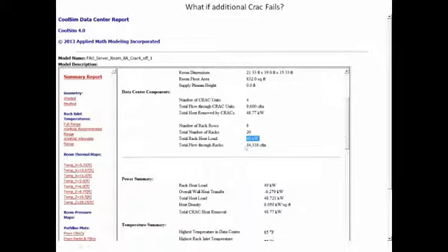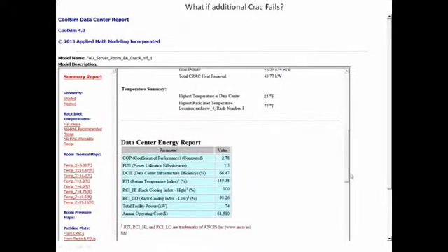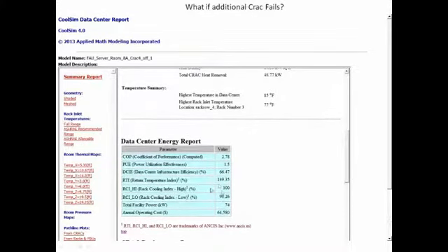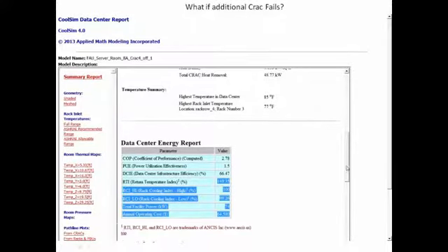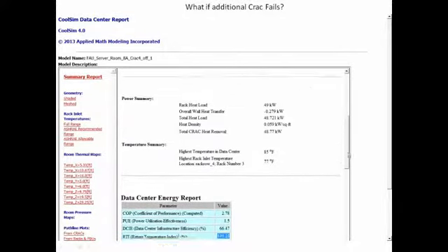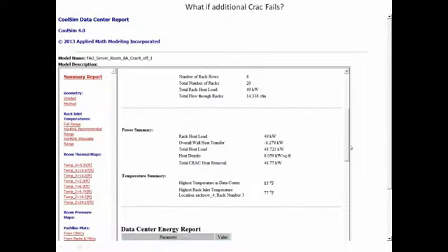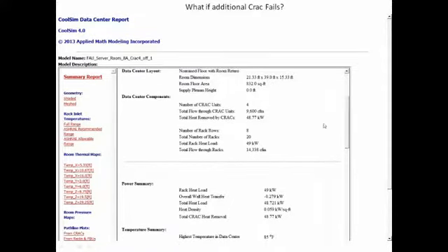But what happens is the flow rate through the racks goes to 14.3. That actually improves things a little bit. But my RTI is sitting here now at 149. I still don't have nearly enough airflow coming through to satisfy the needs of these racks. If we look again, the racks, and they're both on full tilt right now, they're 4,800 apiece, but they only produce 9,600.